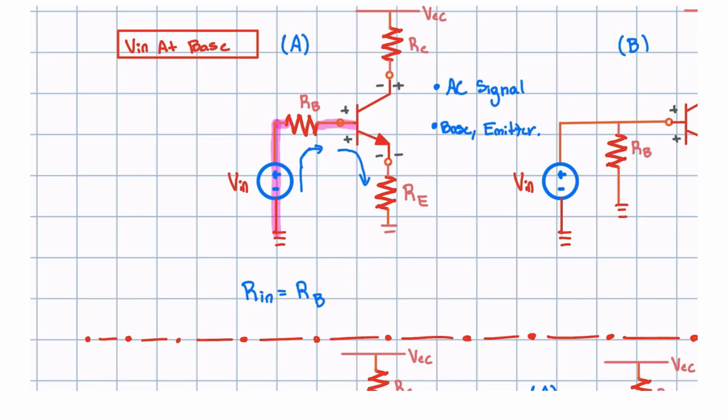As we keep moving forward, we finally hit the transistor. And wait, we need to remember there's something special in this case. Right here at this leg, where the BJT has its arrow pointing to the emitter, there's actually a resistance, typically denoted as R pi. And R pi is something we typically find in the DC analysis before we get to the input or output impedance. So as we get to R pi, we simply include it in the input impedance. We have R pi now.